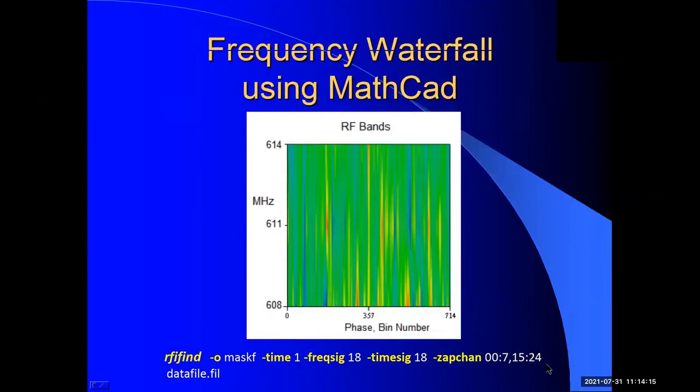And you can do the same thing with frequency by zapping channels, blocking it. Here I've selected just the central channel, which is this one here. And you can see once again, because it's only a 5:1 signal to noise ratio, at least we're seeing components in all parts here. They're at different amplitudes, which is an indicator of scintillation, which occurs in both time and frequency.